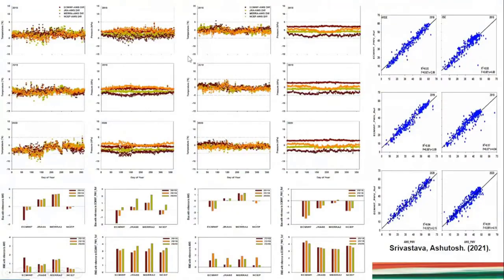This is another analysis, as we were discussing, regarding the ZHD estimation, where data should be there either from the MET sensor or from the various reanalysis data sets. In case of non-availability of a MET sensor near the receiver, different reanalysis data can be used. So we need to see which reanalysis data is more accurate.